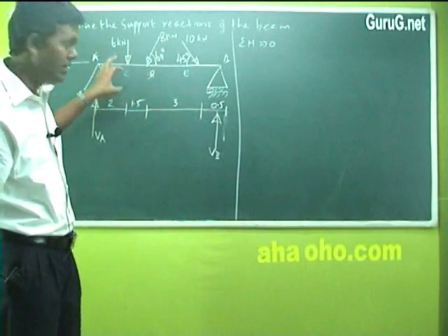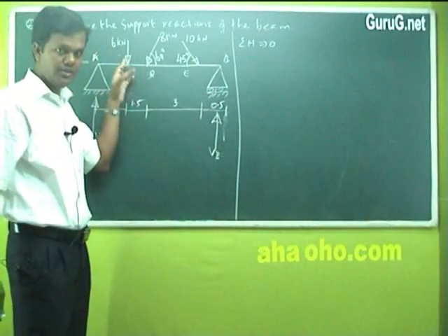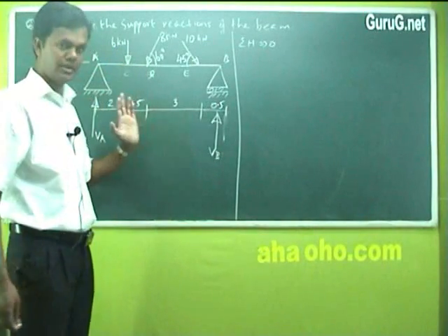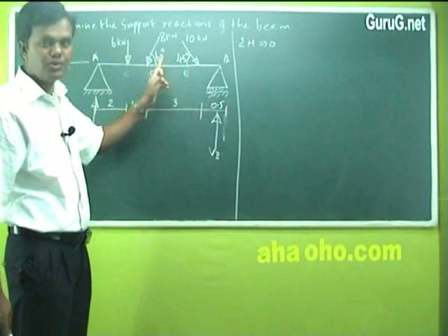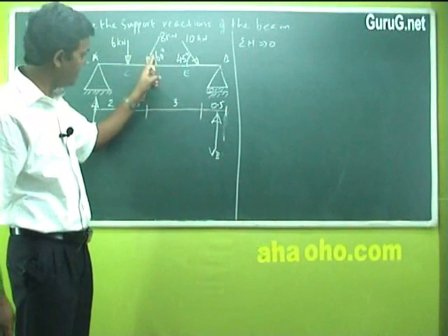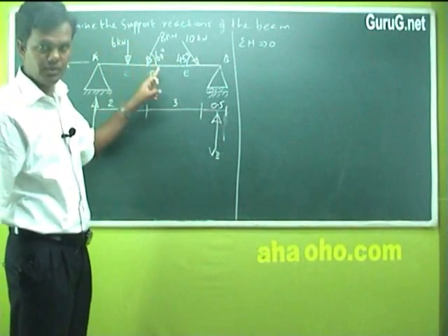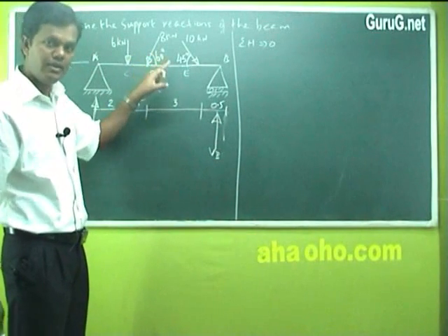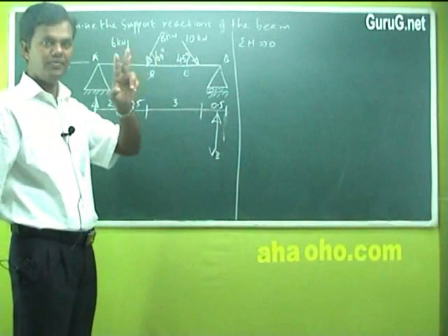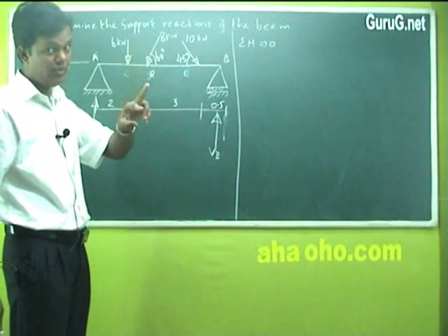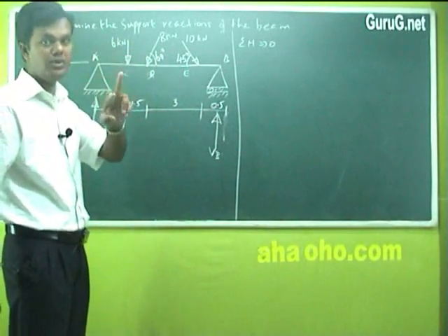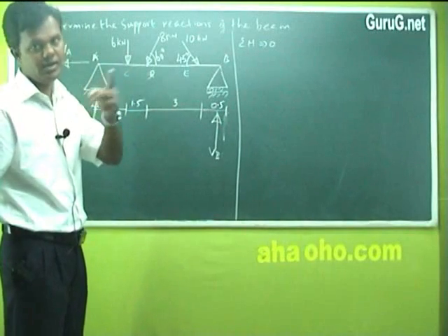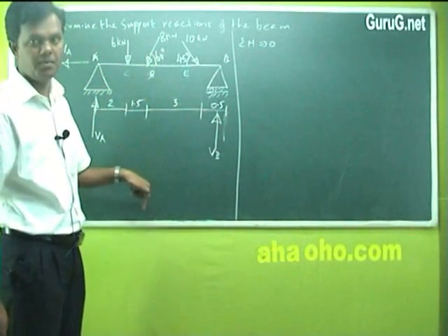Now the next step, what is the modification required here? If I have only the vertical load, that is fine. The arrangement made is right. But there are some inclined loads also. If an inclined load is given, it is our duty to modify it and divide it into two different components. You are resolving the inclined force into horizontal and vertical components, and then start answering the problem.